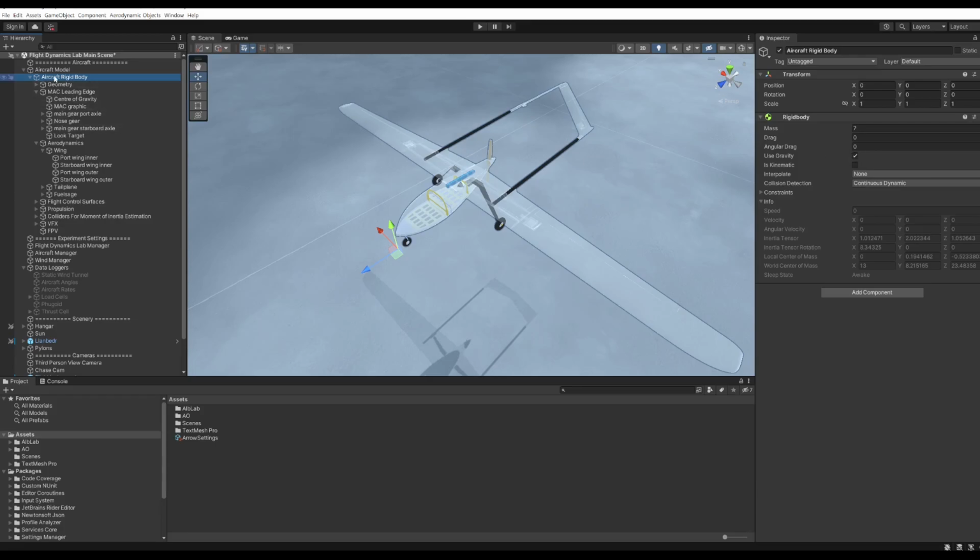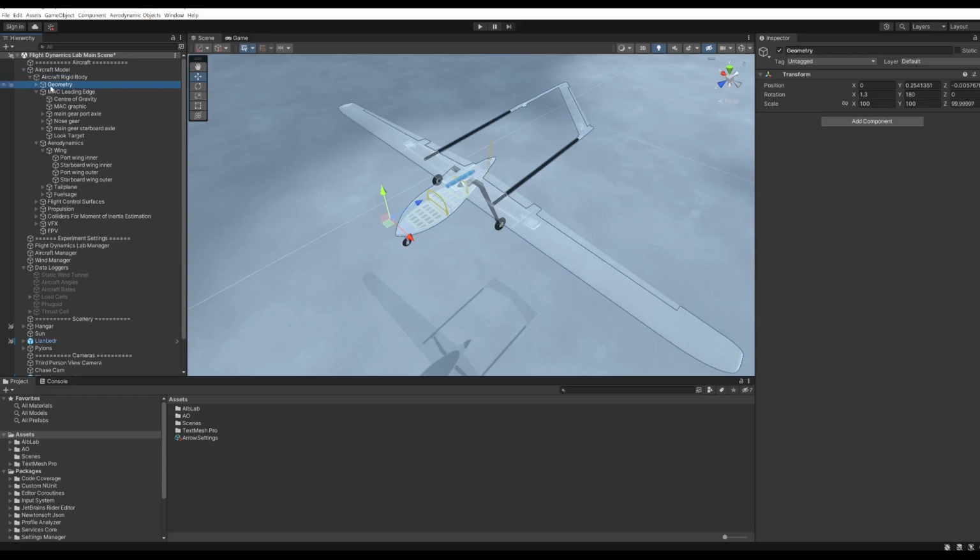And then underneath this node we've got various other bits that hang down from the mass node of the aircraft. So we've got the geometry there, which is essentially the CAD model of the aircraft, and that's really there for people to see the shape of it and draw reference in terms of where things are. In terms of the physics, it's not controlling the physics. The physics is controlled by our inertial bodies we put on and our aerodynamic bodies.